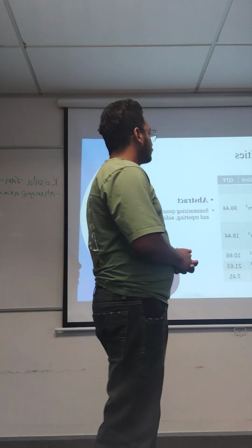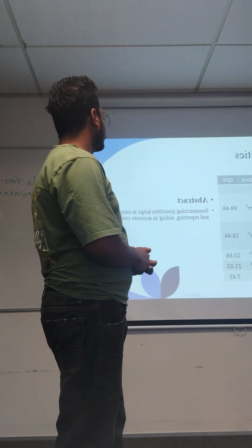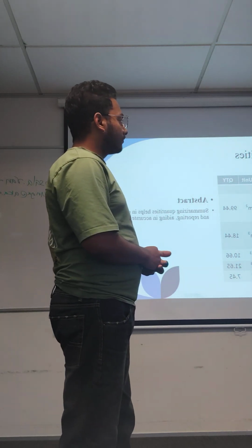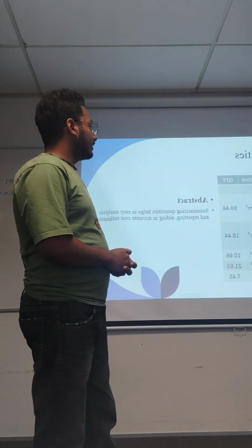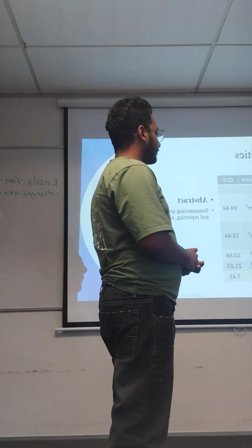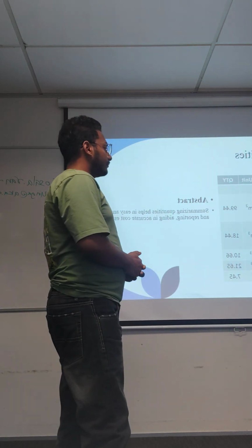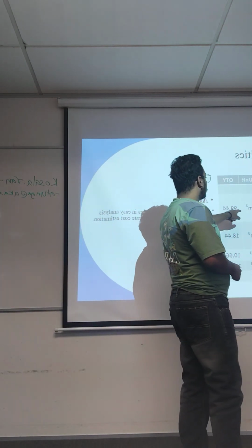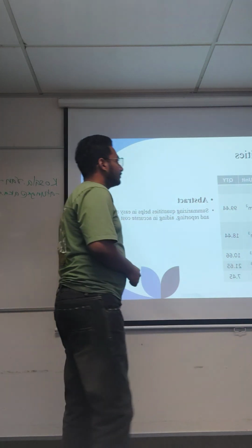Abstracting quantities. Abstract summarizing quantities helps in easy analyzing and reporting, aiding in accurate cost estimation. So earthwork, then ground clearance, first 1 meter length from the center line, and excavation and trenching and footing excavation. Next is excavation slabs, disposal, and backfilling. As you see, in the ground clearance the unit is square meter, quantity 99.44. Next one.